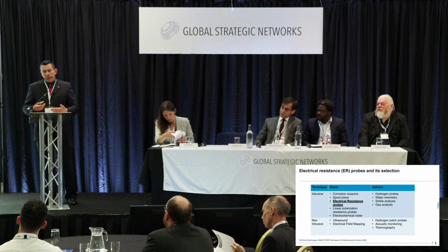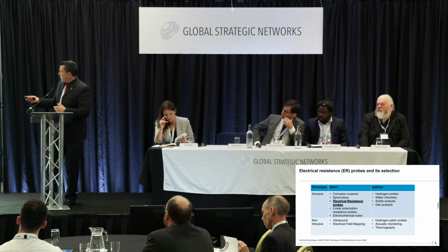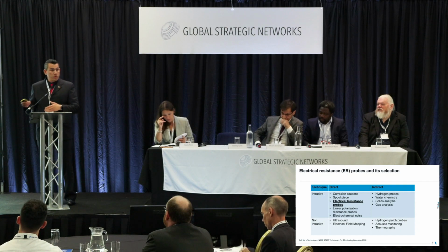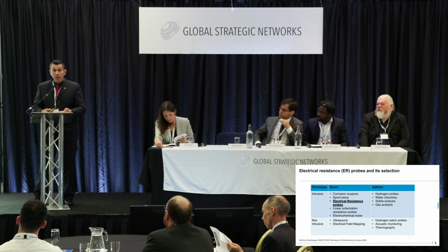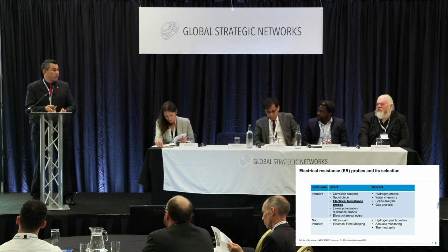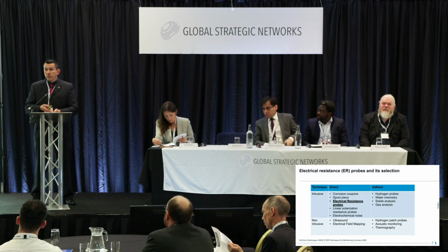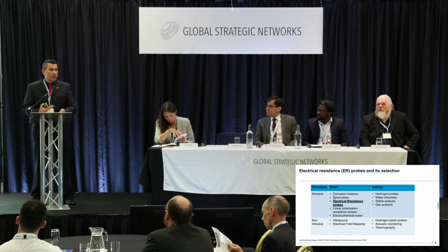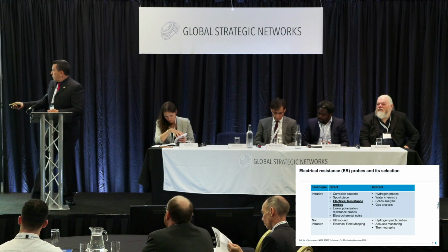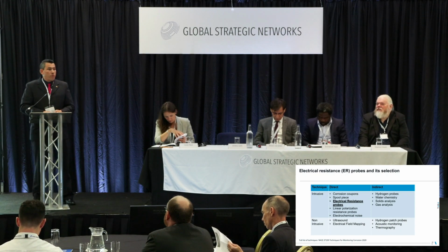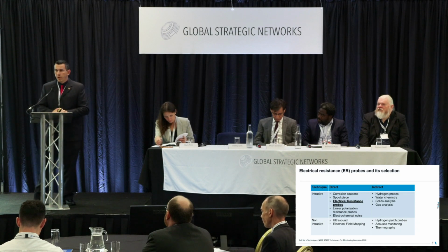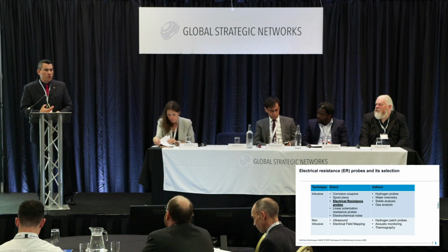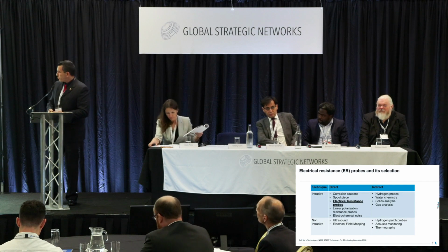Another way to look at this is what kind of technique we want to use, intrusive or non-intrusive. With intrusive, we have the limitation that we need to penetrate into the system to get direct contact with the process. So we need to be in the pipeline, process piping, or the vessel. There are non-intrusive techniques like ultrasound, where you can get information about wall thickness loss from outside of the process, without all the safety issues associated with intrusive techniques.